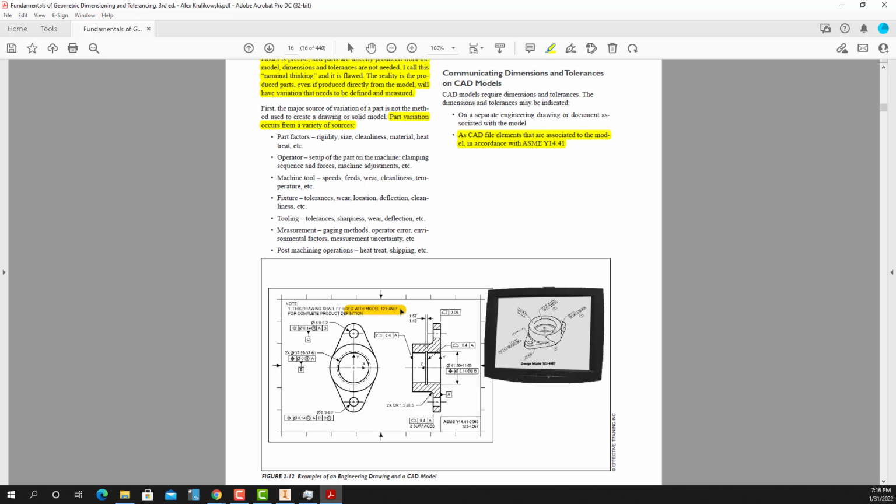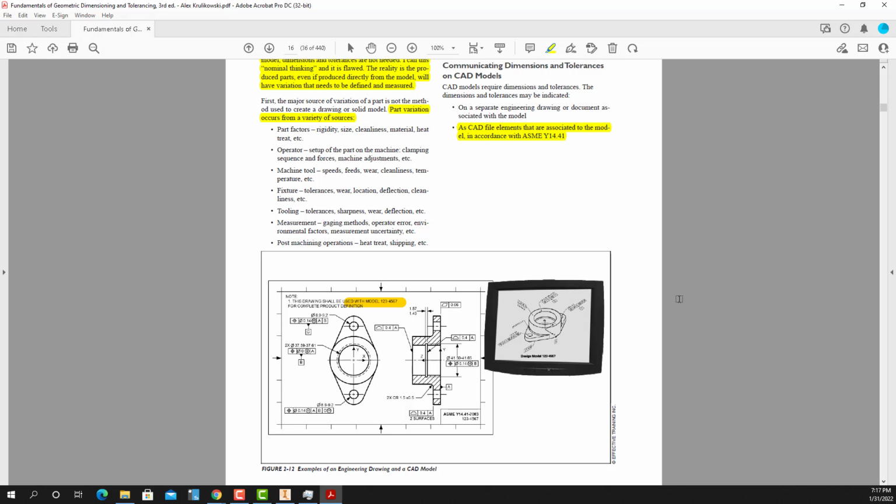Anything specific, and this is critical to function, GD&T, critical to function only, dimensions will show up here. All right, everything else comes from the tolerances specified in the model, and you have to specify that spec. Now I do have that spec if you guys would like to look at that and see what that's like, because that's coming. At some point we won't have drawings anymore. It'll all be in the model. So how are we going to deal with that? And I've seen how manufacturing deals with it, but I haven't seen a lot of design with it.